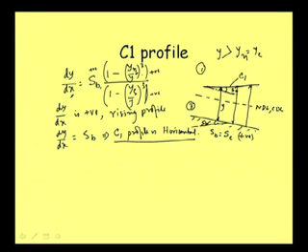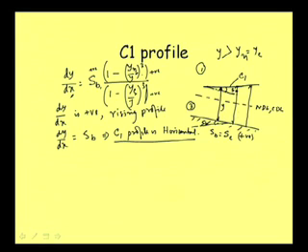That is why we call it a rising profile. That rising term is basically coming with respect to the bed, not with respect to a horizontal line. So whenever we say rising profile, whether it is the M1 profile, S1 profile, S3 profile, M3 profile, or even C1, everywhere rising means with respect to the channel bed, not with respect to the horizontal line. So when it is rising with respect to the channel bed with an angle SB, then it becomes horizontal, but depth is increasing.